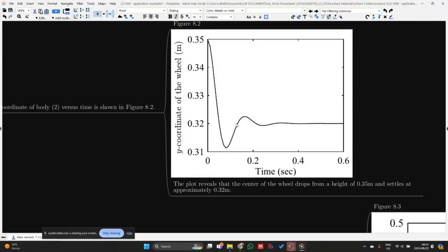So of course there is a fine line between making it too small, so getting a very accurate answer, and then your computational efficiency. If you make it too small, then the system is simply going to run longer, have perhaps more function evaluations as well. But for this type of exercise, we can clearly see the dissipative forces over here, so we don't have to worry about making the reporting time step much smaller than this.